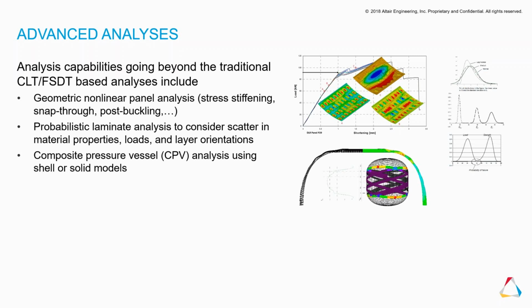We also have capabilities for composite pressure vessels. This is an FE analysis, either using shells or solids. The input for defining the fiber paths in the pressure vessel comes from a filament winding simulation software that we interface with.